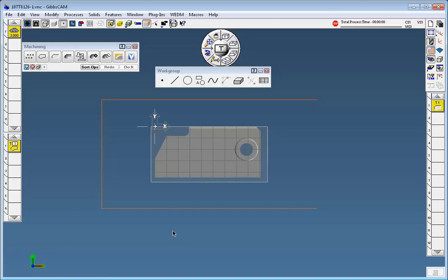This is Jim Green. I'm continuing on a process change to face milling where I'm going to use a line. So I was about to make this line with my mouse with a grid of 0.25. Again, top view or home view will give me the view of my tool that I've selected in yellow. And I just click and hit escape, and I now have a line that can be used for contour milling.